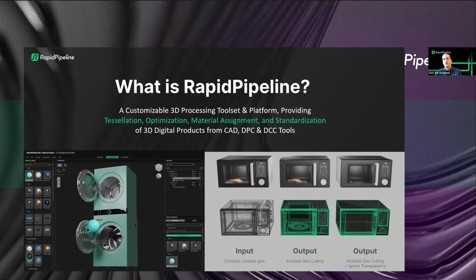You could say, hey, just ignore transparent meshes and treat them as opaque and cull everything that's not seen. And you have a variance for how much things can be seen before they're culled. So if you have things penetrating slightly or seen through gaps underneath different parts, you can control that and say, how aggressive do I want to do my culling?